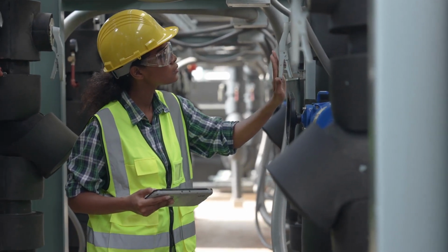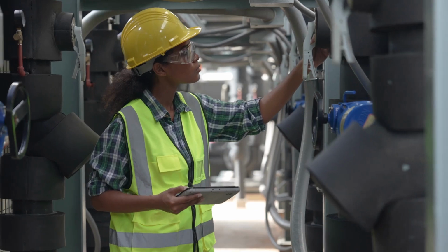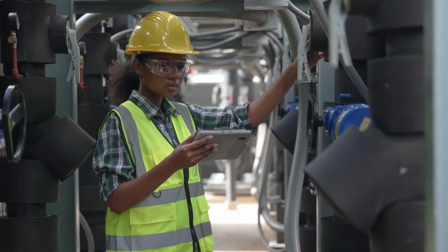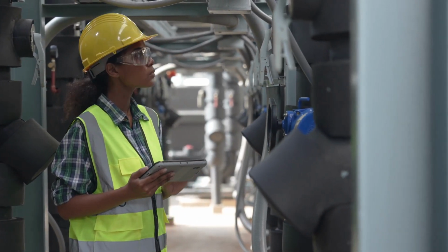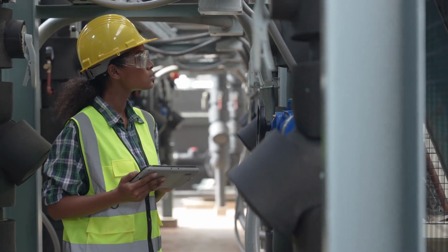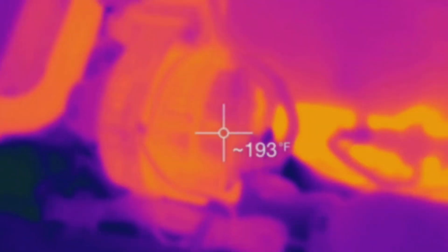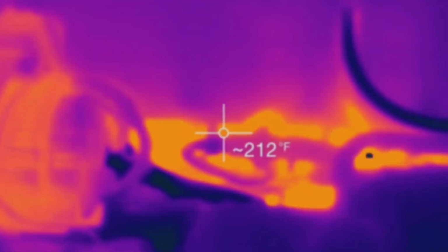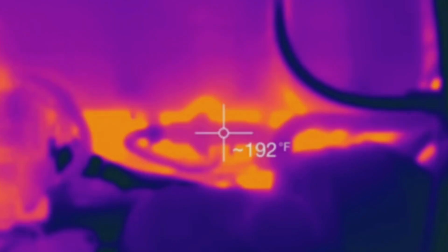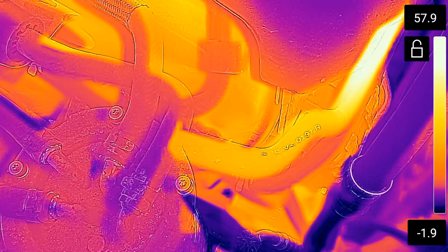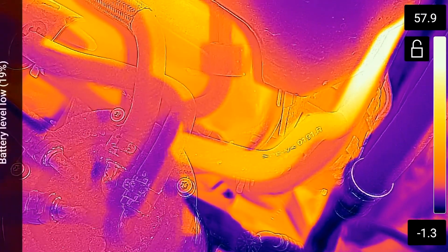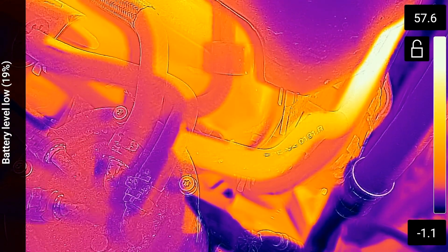Vibration analysis, ultrasound testing, and visual inspections provide additional insights to confirm whether the anomaly is caused by mechanical wear, misalignment, electrical faults, or insufficient lubrication. Thermal imaging serves as the first line of detection, pinpointing potential failures and their exact locations by identifying abnormal heat patterns. However, to fully understand the root cause, cross-checking with vibration analysis is essential.